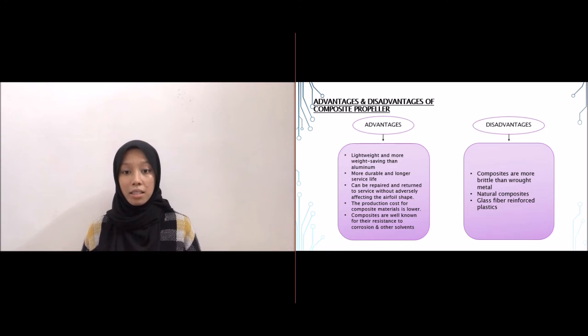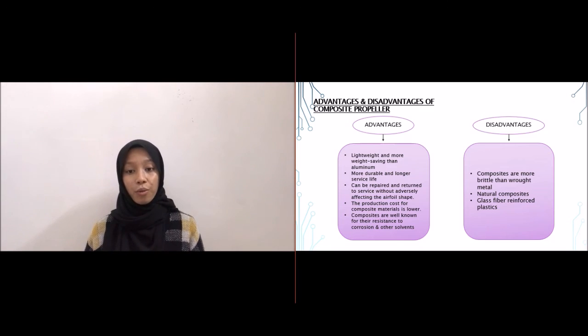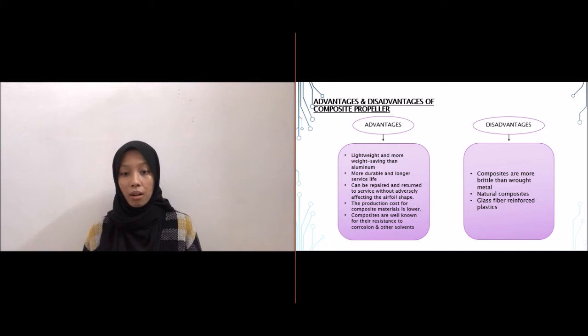In fact, hardened composite blades are for unlimited life, helping aircraft owners and operators to save money and reduce flight downtime. Furthermore, composites are well known for corrosion resistance. The disadvantages of using composite propellers include that composites are more brittle than metal. Although additive manufacturing for aircraft propellers is not commercialized, additive manufacturing is starting to be implemented in propellers for unmanned aerial vehicles, or UAV.